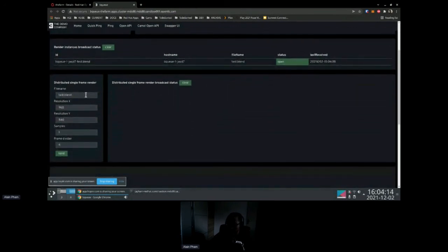And here we can actually run a render. To explain very quickly the parameters for rendering, what's important is the resolution, and then there's this samples configuration here. Blender is a ray tracer. The more samples you give it, the more rays of light it launches. It's simulating rays of light in order to get the rendering done. So the more samples we have, the nicer the image looks, but the more costly it is in terms of compute, right? So let's just run a smoke test and see what's going on.